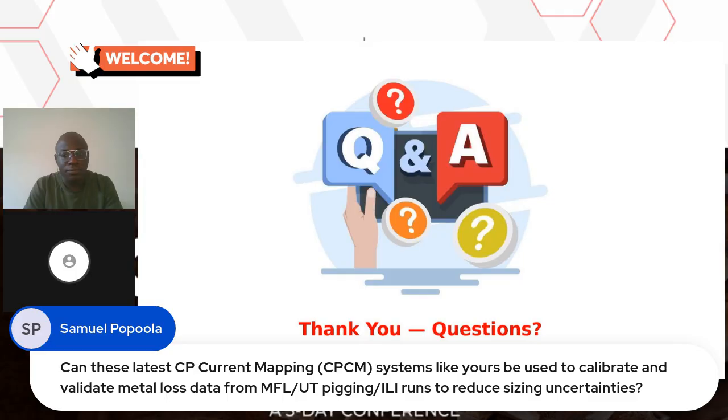If you are seeing potentials which are protected, and your MFL or UT is telling you that these places have external corrosion, then the question is, are we having a shielding effect? Is it the coating? Because this has also happened over the years. We've had pipelines with seemingly good potentials that have failed because the coating was shielding the pipeline from the current. So when you combine this automatic monitoring with your MFL, your UT, and your ILI runs, you perfectly understand what's happening in your system, and then you can make excellent deductive actions based on what you are seeing.